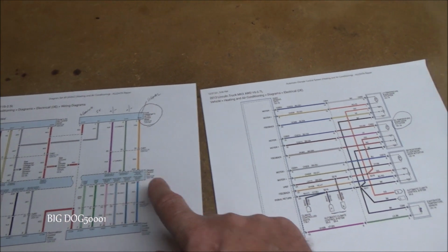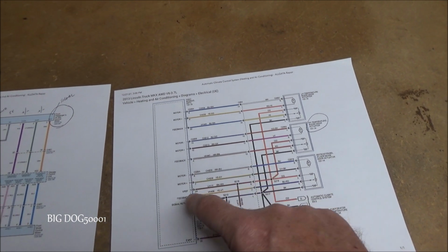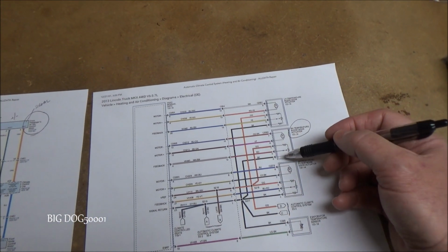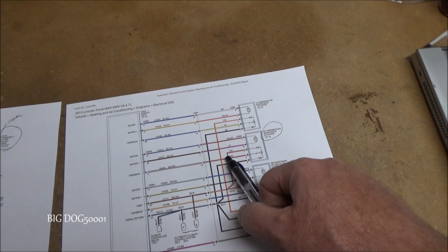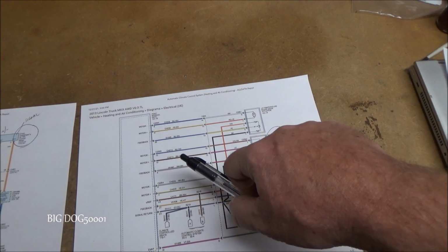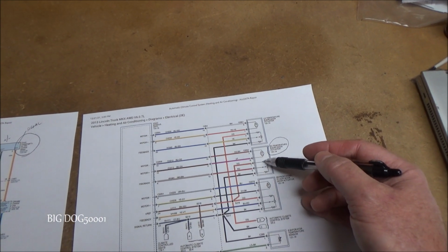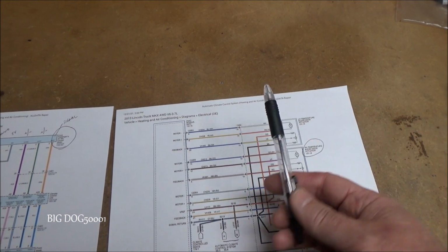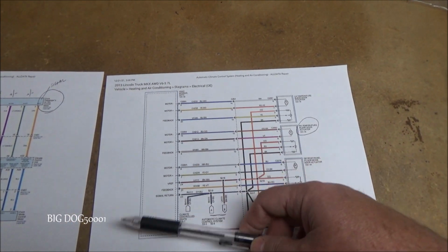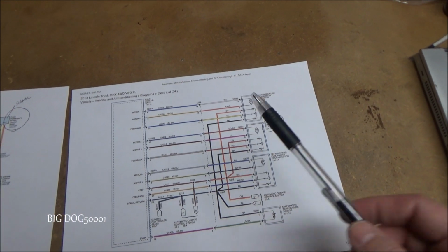Typically, these signals are going to be between 0.5 volts and 4.5 volts. So between roughly 1 to 4 volts, give or take a little bit. That's what these things are. They're changing the 5 volts that's coming in when the potentiometer, or whatever they have inside there, is moving. It's just changing the resistance, which changes the voltage that's going back. We want to see 0.5 volt to 4.5 volts. We don't want to see 0, and we don't want to see 5. It's typically going to be more than 0 and less than 5 on a good working system.